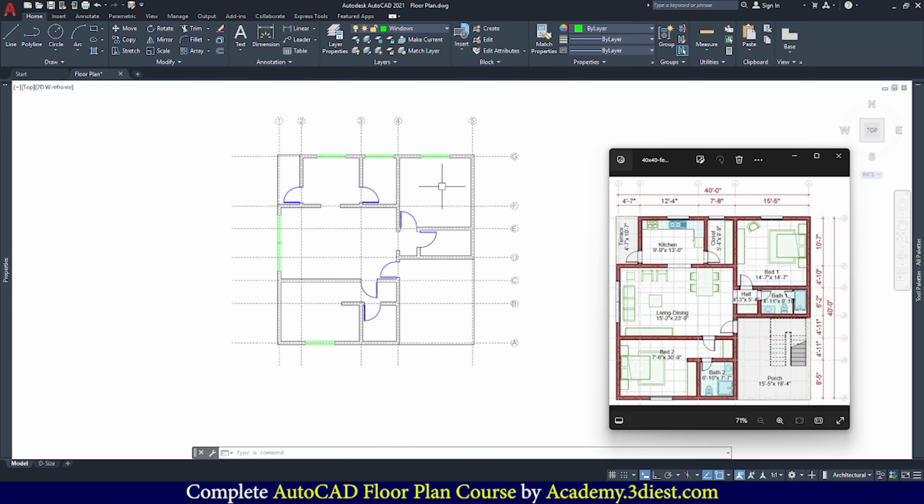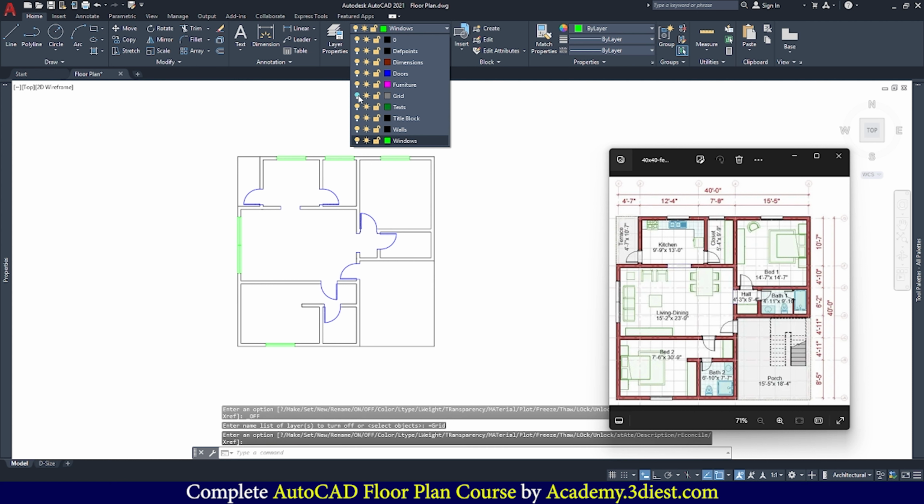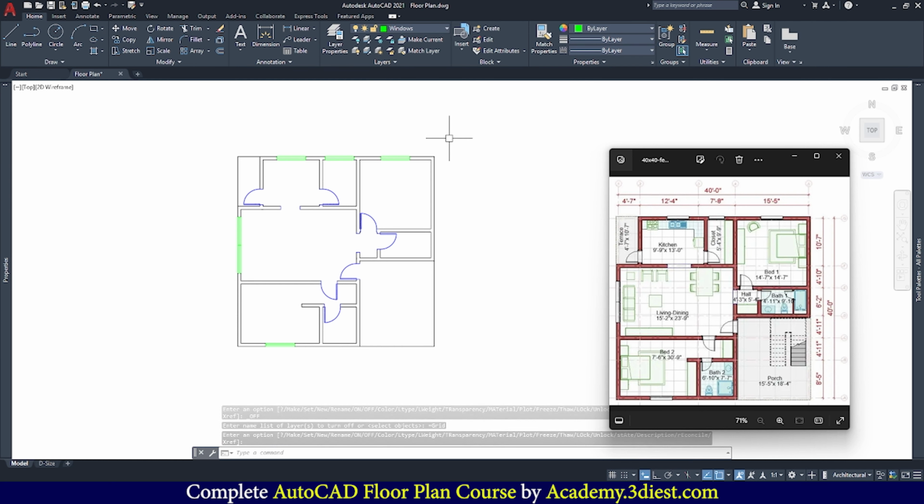Now the next task is to add these annotations to our floor plan. For that, I will turn off these grid layers since I want to work with the annotations only. I will expand these layers, and move on to my grid layers. Since the window layer is active at this moment, I can turn off the other layers. If I simply turn off these grid layers using this bulb icon, here you can see all things related to grids just got hidden.